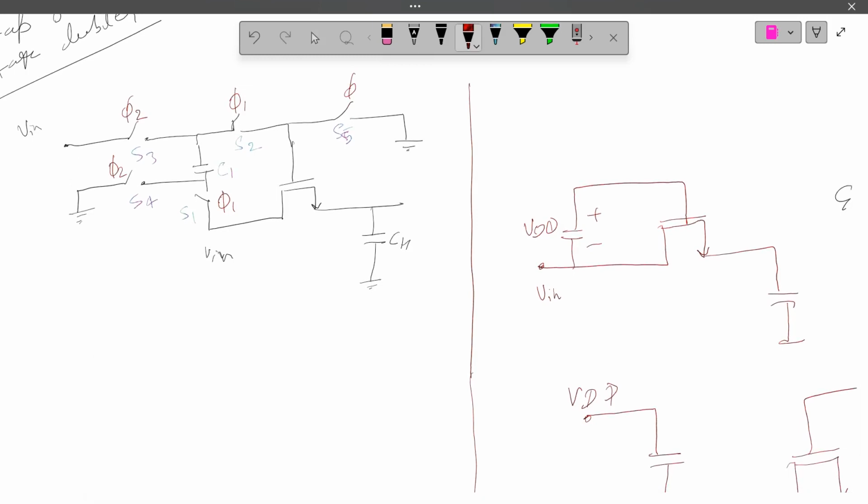As I explained, in future circuits we are going to use the transmission gate. A transmission gate is the circuit where if we apply low voltage or high voltage, it will pass both of the values, right? So at the switch S1, which circuit is preferable to add here? Because we don't know what kind of Vin we get, either 0 or 1. So we can put S1 as the transmission gate.